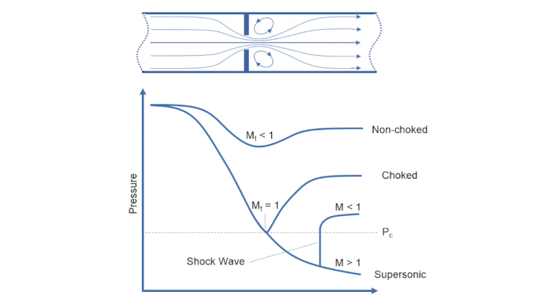This is because the pressure on the inside of the line is typically 80 to 100 pounds, whereas the pressure on the outside is atmospheric, or 14.7 pounds per square inch. This creates a pressure ratio big enough that the flow going through any leak is going to have what we call choked flow, and have a Mach number of exactly 1.